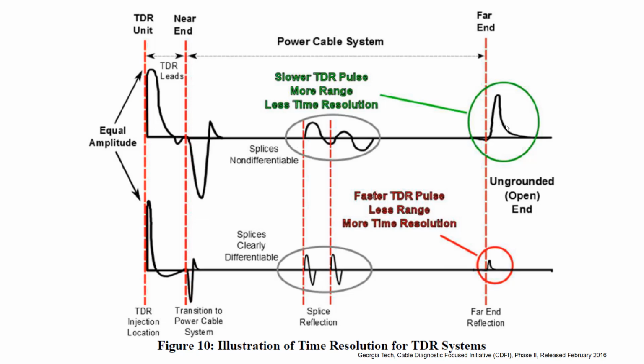At the same time, the faster signal attenuates very fast, therefore the range becomes less. The range of testing can become less. You cannot have longer cables tested using this. But with a slow signal, which has higher pulse width, you can test longer cables also without much attenuation.